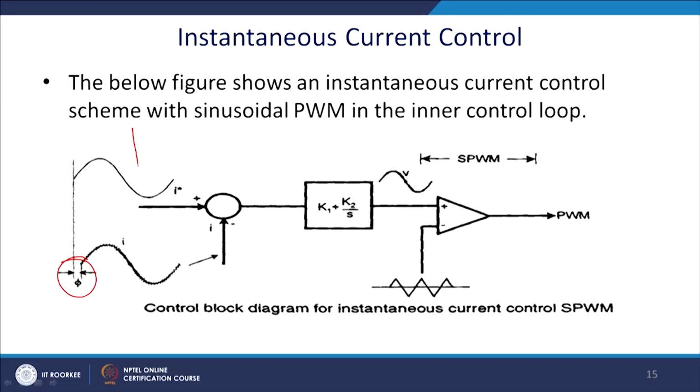For this active power filter you may have this kind of peaky signal. This will be the reference, and you have to track this reference. Essentially for the shunt active power filter you have the harmonic contents of 5th, 7th, 11th, 13th. So, you have this kind of reference and it has to track that reference, not necessarily in all cases. This will be sinusoidal, and that value will be fed to generate PWM in the case of the instantaneous current control.